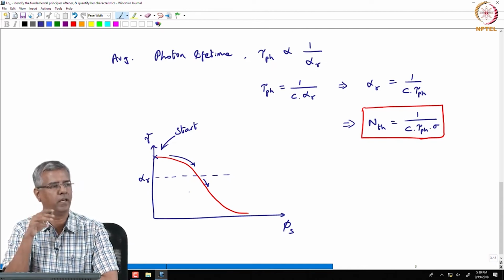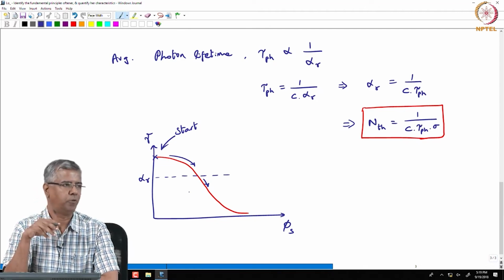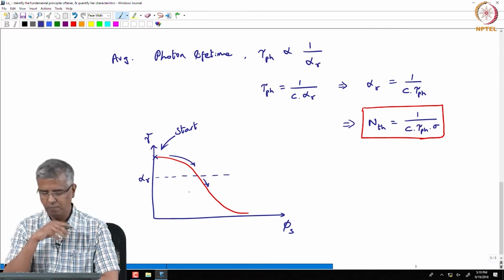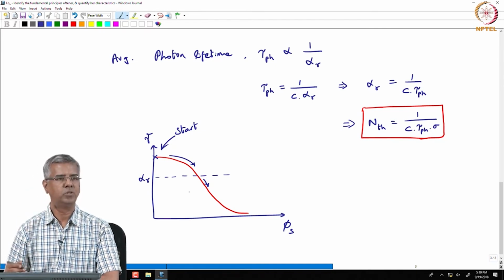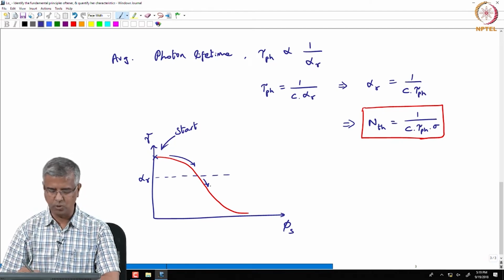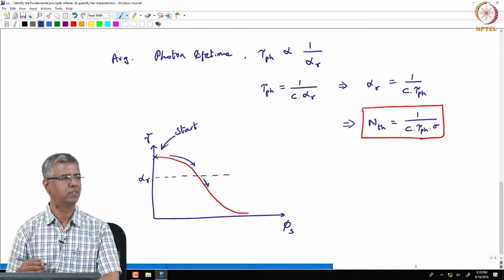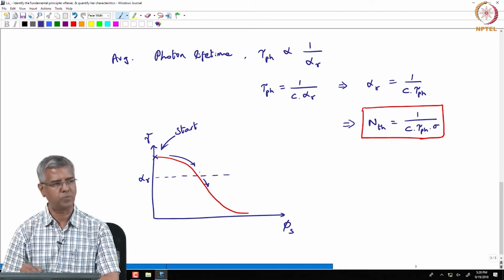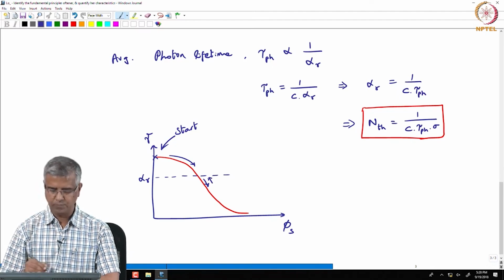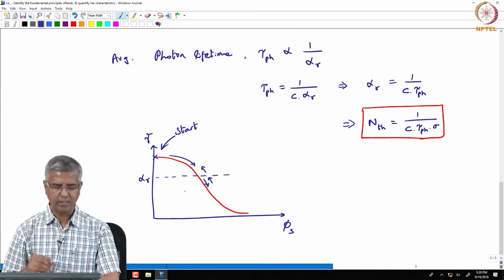So, you basically have spontaneously emitted photons, and those photons are going to be very few, because of which you go back to the small signal regime. So, you start going past here and then you realize, oh no, we have very few photons coming around. So, the gain actually corresponds to the small signal gain. Then you go up, and you may go past this point also, but then as you build up photons, you are coming back to this point.